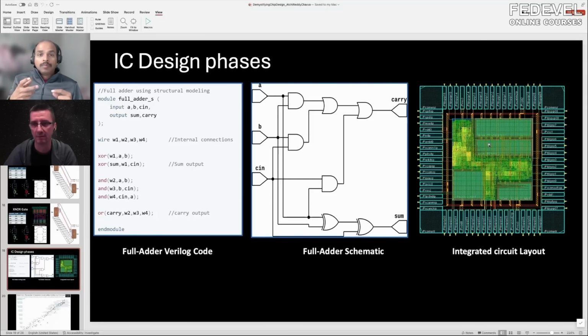To explain it, if you remember the power equation, the power is CV squared, your capacitance times voltage squared. Now, the lower the voltage, you will see a quadratic reduction in the power requirements. That's the reason why we want to shrink the devices, so that we need less power, and then we could do a lot more for the same power. Even the heat is all the power changing to heat. Yes, exactly. That's the reason why we would like to lower the voltage, and then we get the benefit.